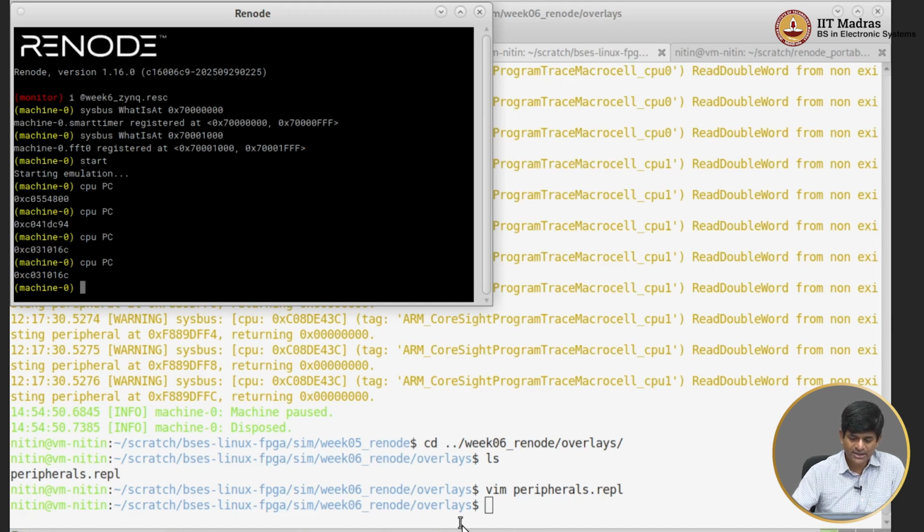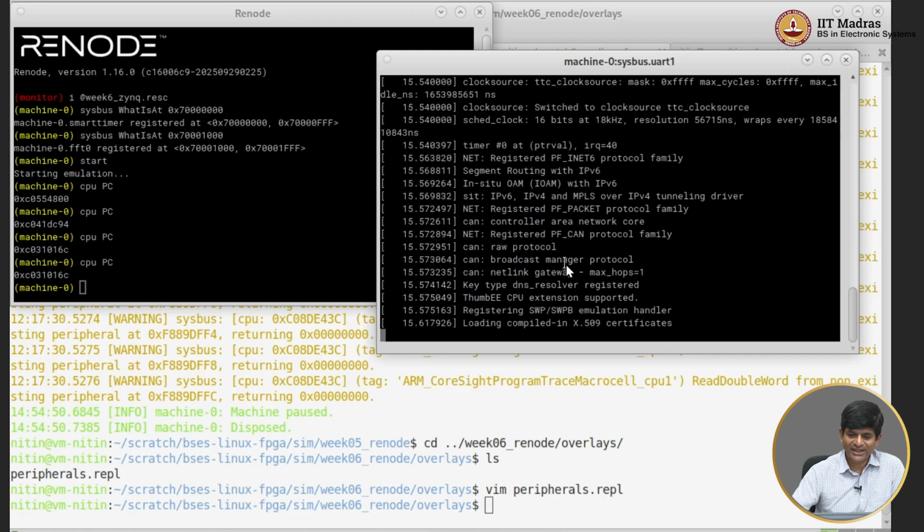What is important to us is that a bunch of messages have been getting printed out on the screen, on UART1, also on UART0, right? But UART1 is the main thing that's of interest to us because that's the one that's actually mapped internally inside the kernel as the actual console for this system. So we just wait a moment for the system to finish the boot up process and finally drop us into a shell where we can start typing commands.